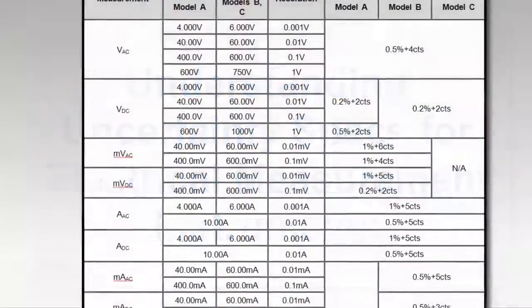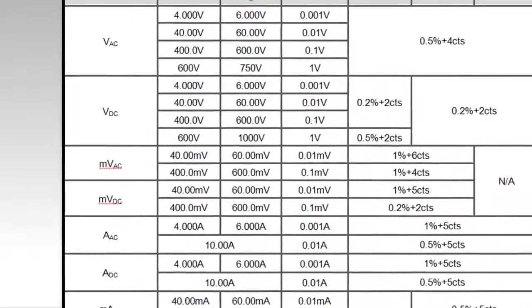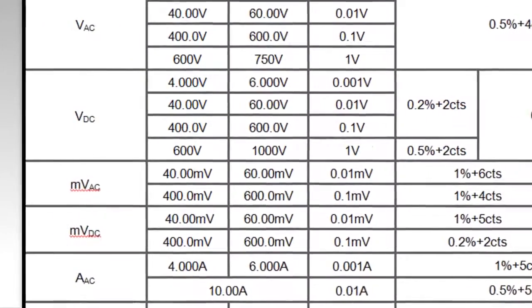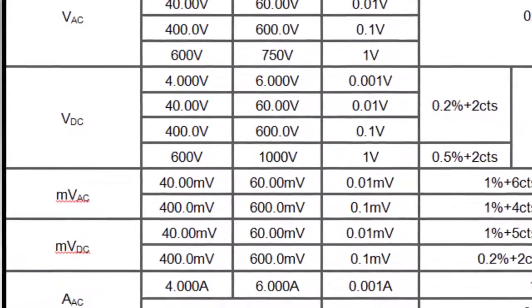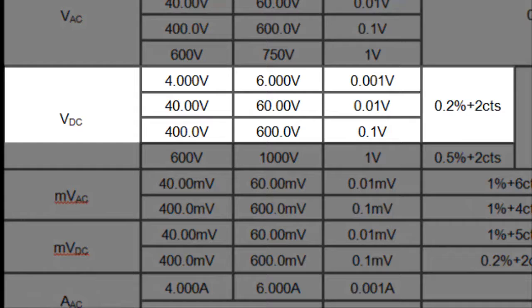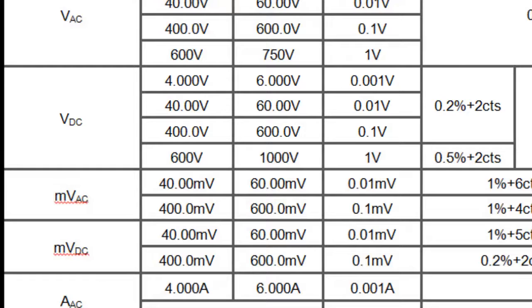Unfortunately, the relevant specifications for electrical measurement equipment are often expressed in terms unfamiliar to less experienced users. For instance, the specs for a digital multimeter may list its uncertainty for measuring DC voltage as plus or minus 0.2% plus 2 counts, with no further explanation about what this formula means and how it can be applied to the displayed reading. This can make it difficult to compare the accuracy of different products, or even know whether or not a particular instrument is suited to your requirements.